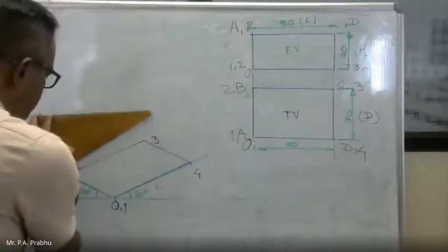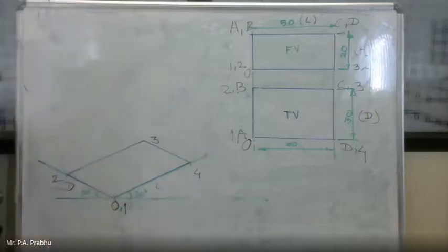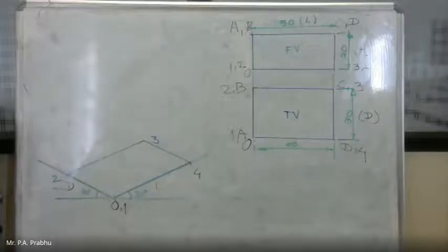And remember, draw with a faint line. We have to show the visibility here. Some surfaces will be overlapped or hidden, and we have to erase that at the end. So I have completed the bottom surface of this object, that is the width and depth. Still the height we have to mark. Okay, up to this step, anybody has a problem? You can ask me.